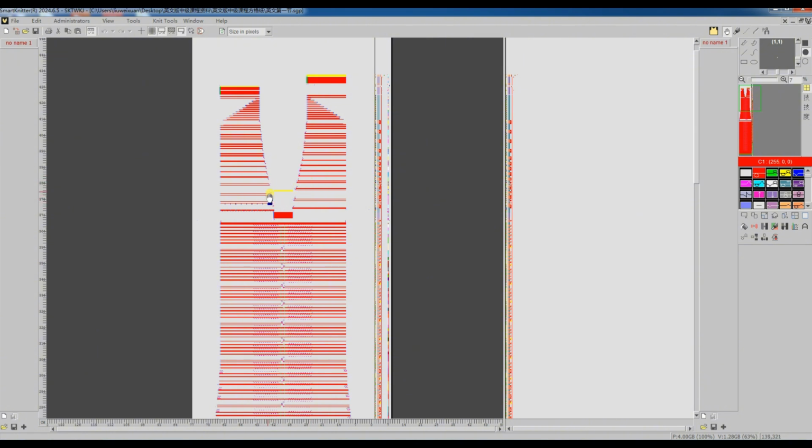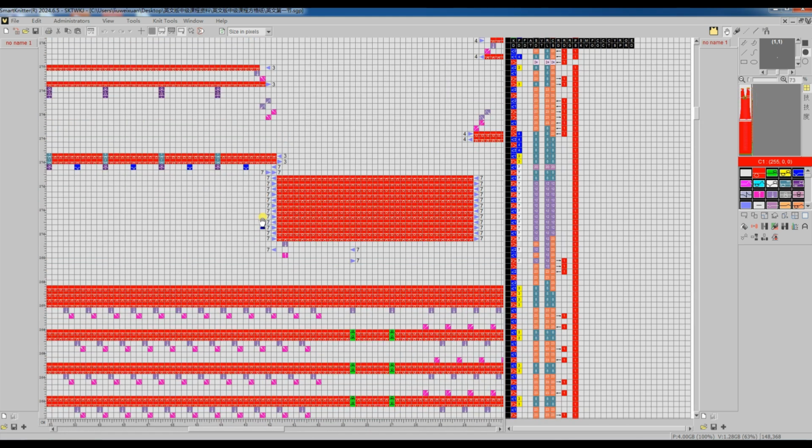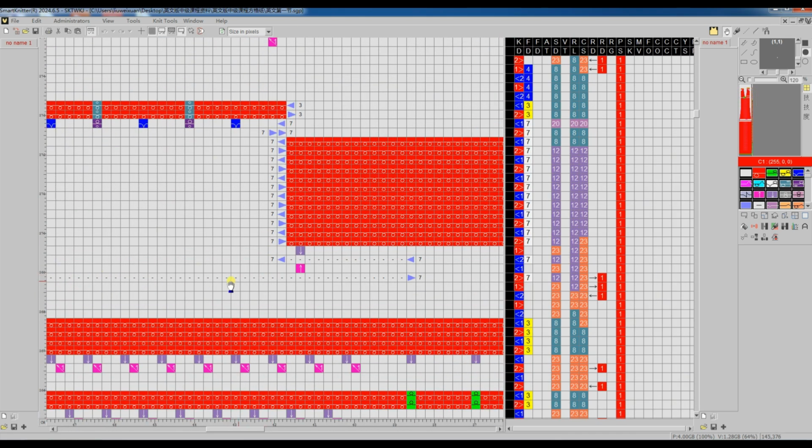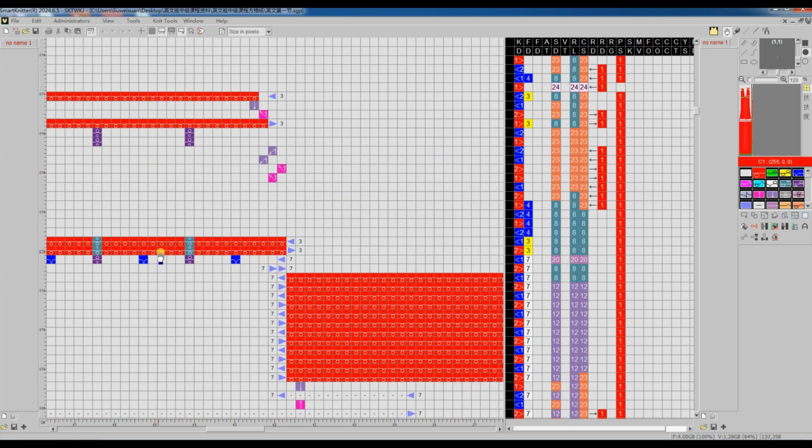Going to the neckline bottom. Cast off here with ravel yarn feeder 7. Feeder 7 comes from the left side. Secure the incoming yarn with transfer, then knit to cast off the neckline bottom. After that, feeder 7 is brought out of the knitting area again with intermittent tucks to secure the yarn end. After 4 revolutions, the tucked stitches from feeder 7 are pressed off.